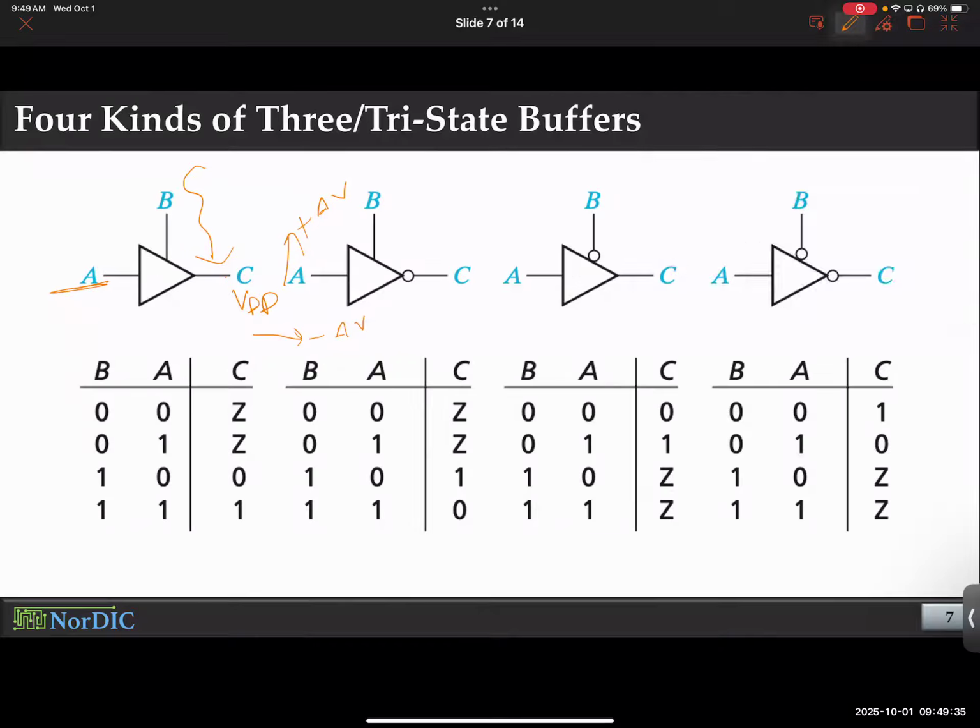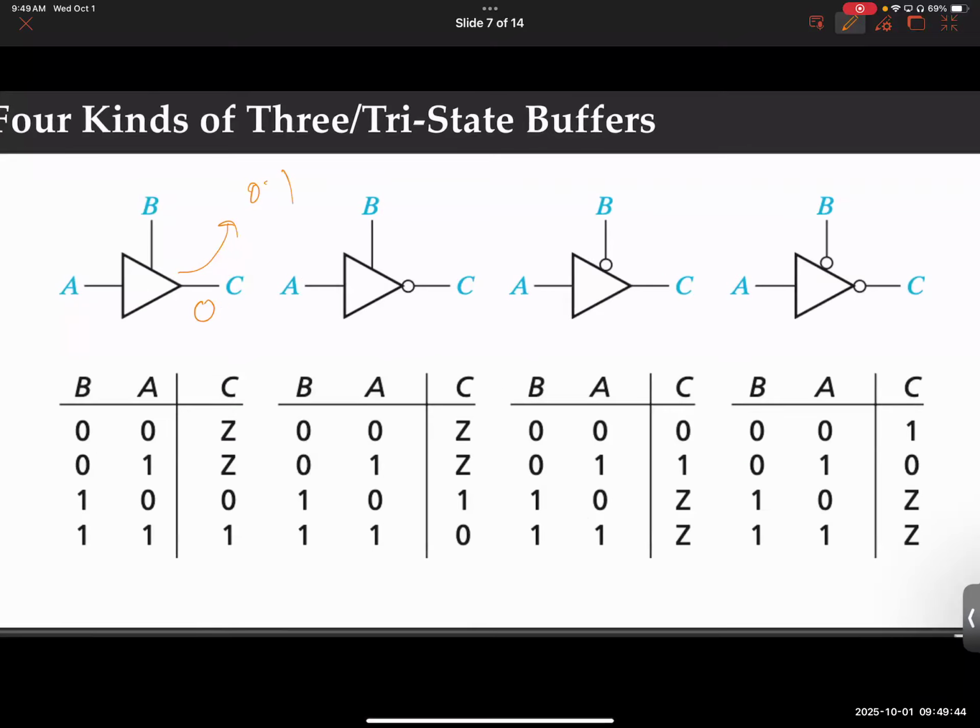If it were, say, 0, instead of staying at 0 because of random fluctuations from the environment or interference, it could go up to, say, 0.1 volt or something like that. It could change. But if you drive this to 0, it will remain 0. This environmental noise will not change it at all. Does that make sense? That is the difference between driving and floating a node.